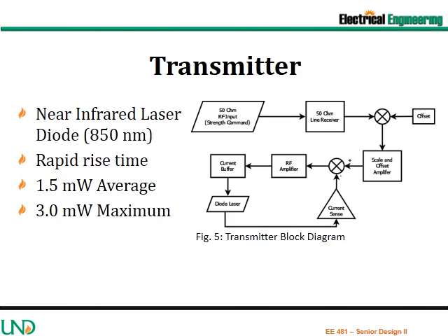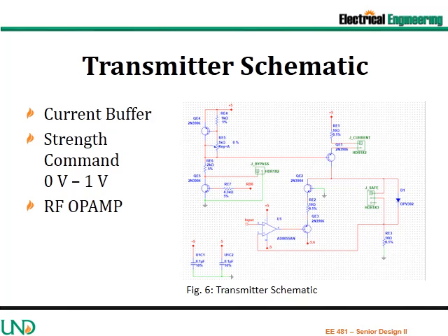The transmitter laser diode transmits at 850 nanometers. This is a relatively quiet place in the optical spectrum that allows the signal to be differentiated from background with greater ease. The high-speed op-amp unfortunately does not have the required voltage range to drive the laser diode directly, and sense the current as well. This forced the requirement to utilize a transistor to drive the laser diode. The BJT was chosen specifically because it is a current-controlled current device. MOSFETs have additional capacitance which reduces the speed and raises ringing.